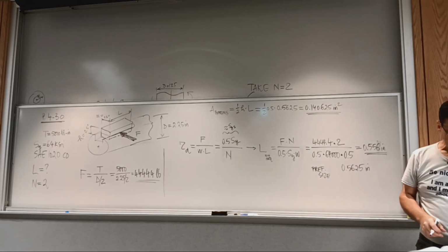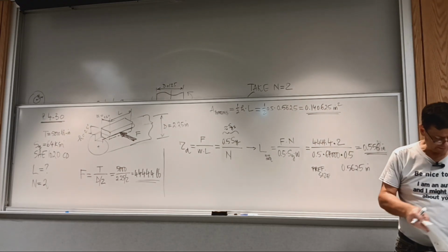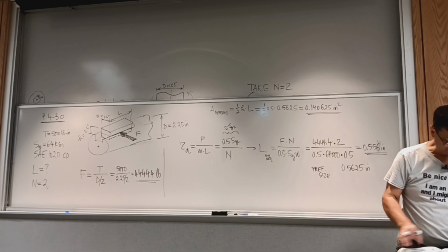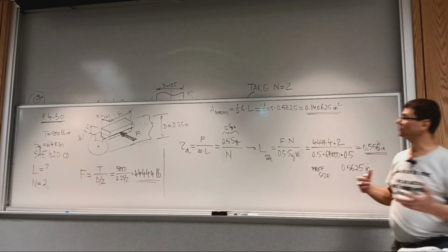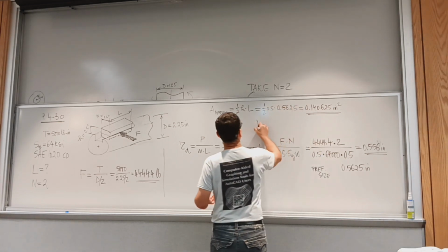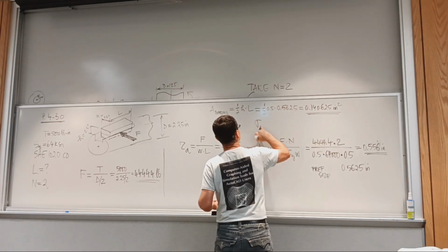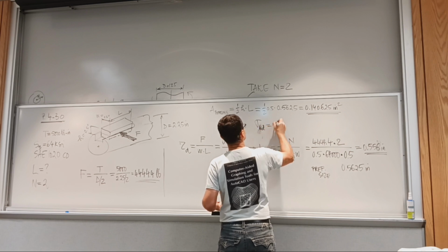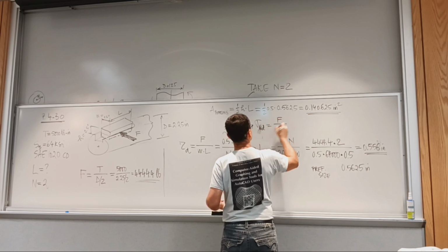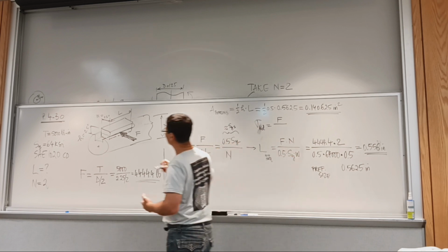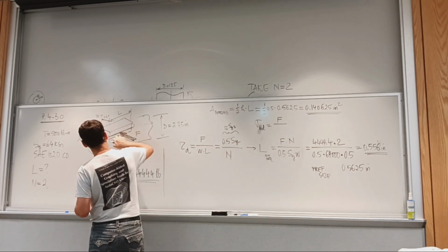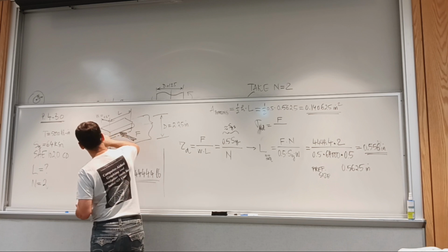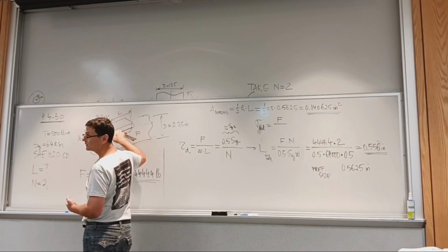And well, here they go into more details. So American Institute of Steel Construction, allowable bearing stresses. So let's see what the chapter says. Otherwise, you just calculate the bearing stress, sigma BD. You just take that same force that causes shear. And like I said, they differ. There will be a bigger force causing the bearing stress on the lower part than on the top part. It's how it is.